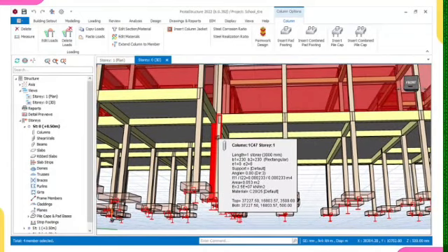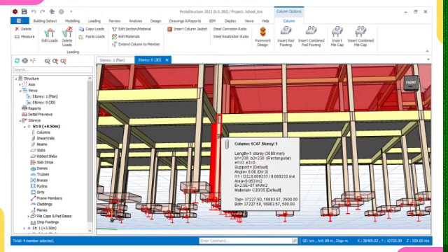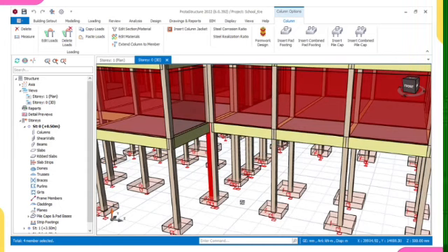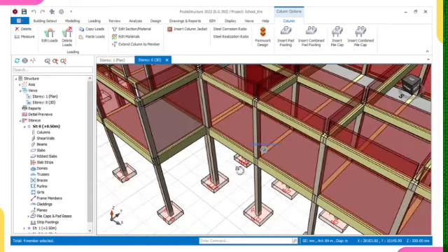With this space now, the concrete can expand and contract without causing cracks on its members. And if you can see, there is no expansion joint at the foundation. Why? At the foundation, we have the soil serving as an insulator, meaning that there will be no heat. The temperature is moderate, because the soil is causing the concrete to have a moderate temperature.